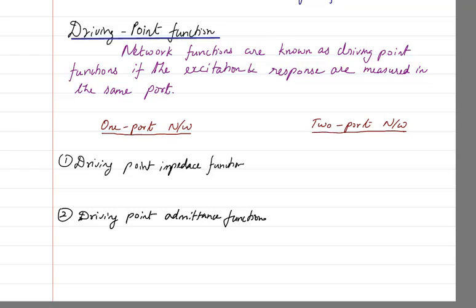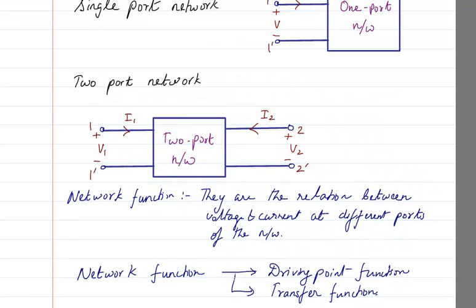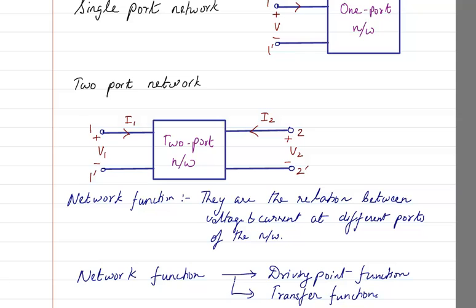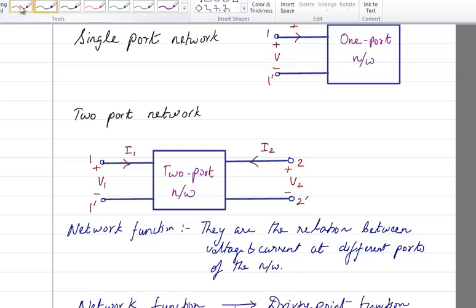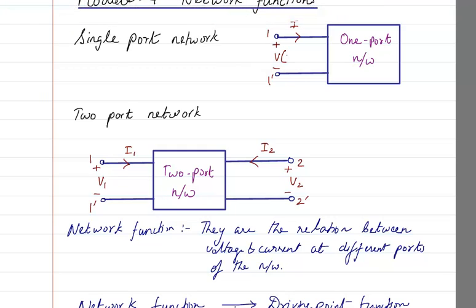It is basically, always we take it in terms of Laplace. So we know impedance is Z, it is given by V by current I. So here we are having Z of S, and we write it as V of S by I of S. What you should always remember is that whenever we are writing V1, I1, it is all with respect to S. So let me write that. This is V of S, I of S. This is V1 of S, I1 of S.